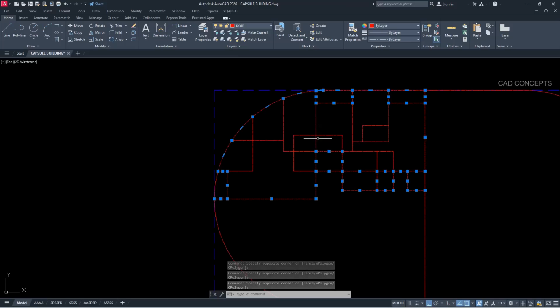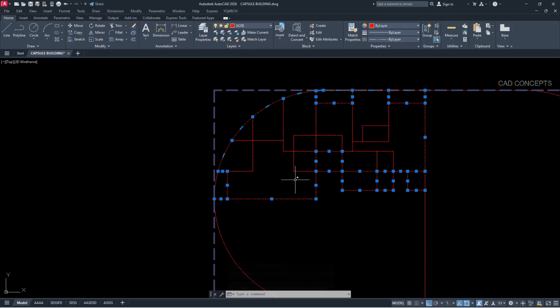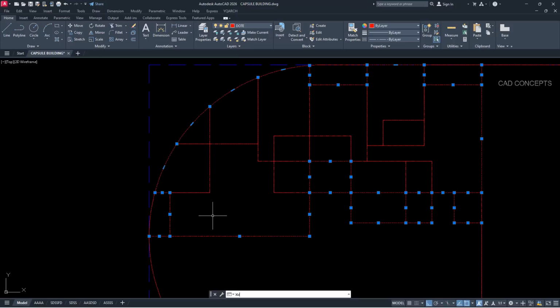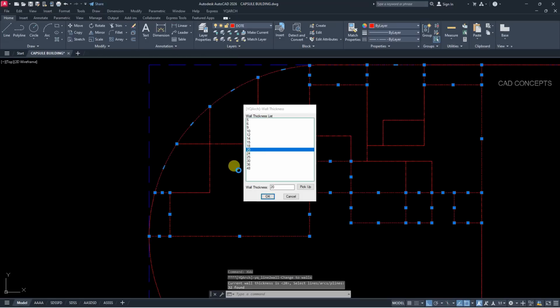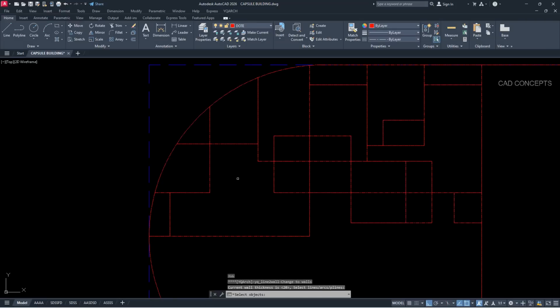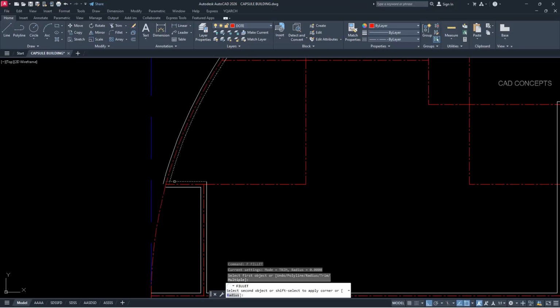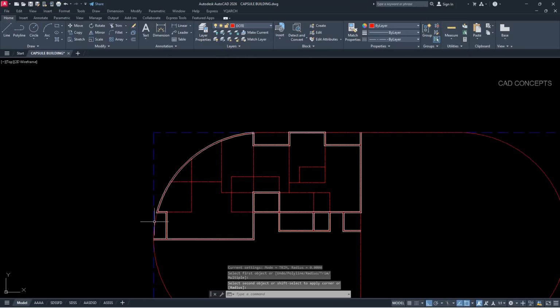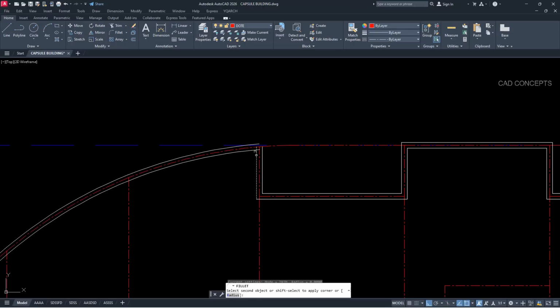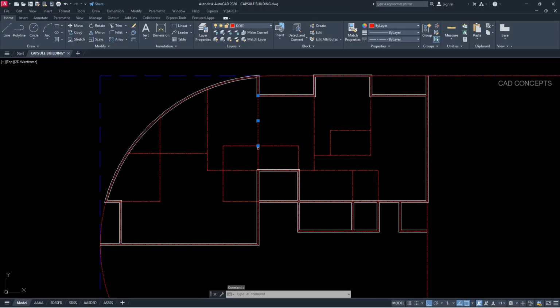So these walls 20 centimeter we will consider. Type XWW, choose 20 centimeter, enter, repeat again, select previous, enter. So these are the walls 20 centimeter. And just arrange wherever you are not getting smooth connection with wall. Here also and here also. Match everywhere perfectly. Inside will go 10 centimeter, and flat to flat exactly 20 centimeter. So the rest all will go 10 centimeter.